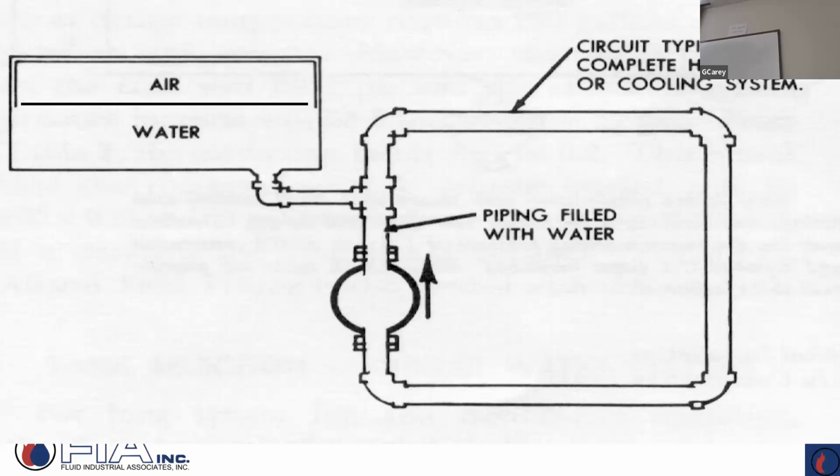But I'm a pump and I'm going to create this pressure differential. So in this orientation with this arrow saying I'm pumping that way, if that pump came on and you had gauges on the discharge and on the suction, you'd watch the suction pressure drop by a function of whatever the pump could develop, whatever the pump head was. Because the discharge really is locked because he can't change the pressure there. So yes.